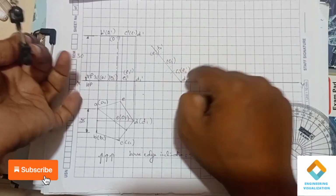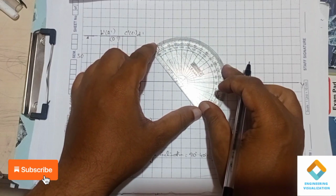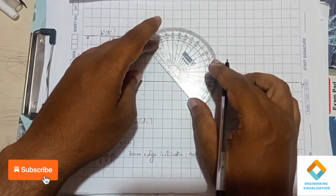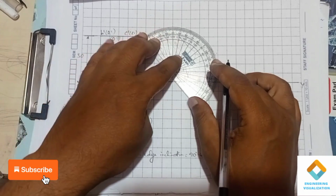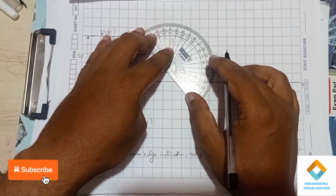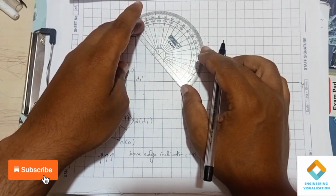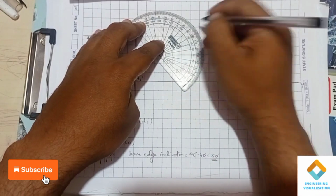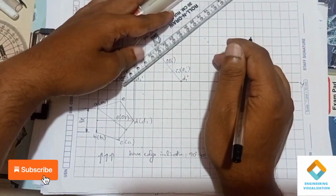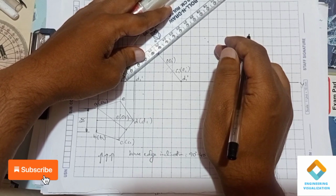So what we do, we are going to use the protractor and mark for angle 90 degree for all these reference points. Okay, place the protractor here, mark for angle 90 degree. Fix up for the C1 dash here, mark again 90 degree. Same way mark for the O1 dash axis point, mark again 90 degree, then fix it for the last corner point. Again you mark for 90 degree. Okay, now using the scale, we should be drawing for that 90 degree a length of 50 mm, because it is the same length we should copy here. So draw a line of length 50 mm.